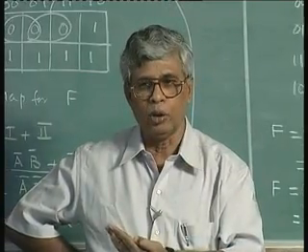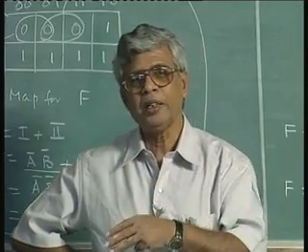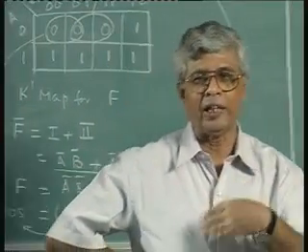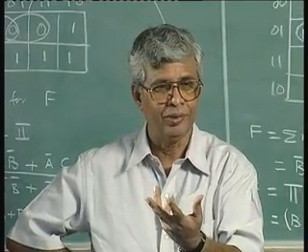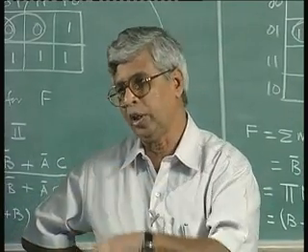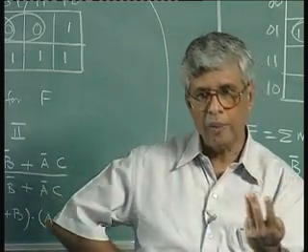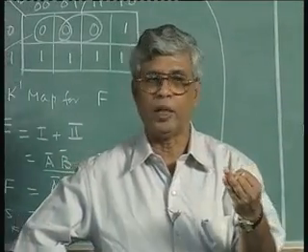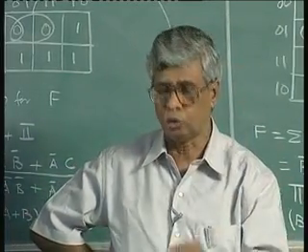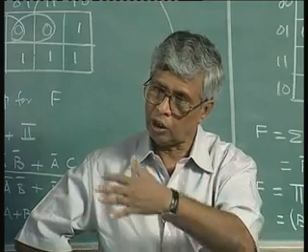There are 8 combinations, I told you, 3 combinations for which the output has to be 1, I am worried about that, I am concerned about this. 3 other combinations I say 0, and the other 2 I do not worry about. I can combine all these 3 plus 2, 5, and say for all other 5 combinations I do not care about the output, what does it matter to you if the output is 0? Okay. So I can say for all other combinations other than these 3 for which I want 1, output is 0. I can do that. That means I will have more zeros, fewer ones. Or I can say, since I do not care about the output, those 3 combinations for which I want the output to be 1 and those 2 combinations for which I do not care what the output is, all the 5 combinations I will always produce output of 1. I will make sure for the 3 combinations for which the output should not be 1, the output will always be 0. That is also possible, it is a reasonable argument, both are reasonable arguments.